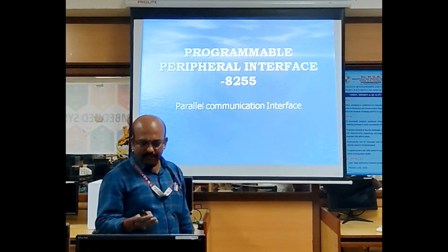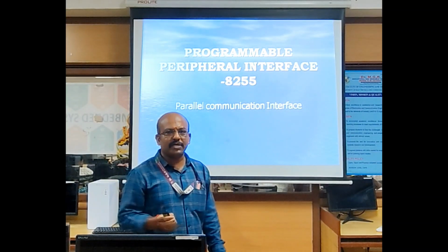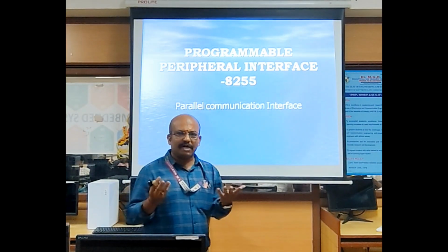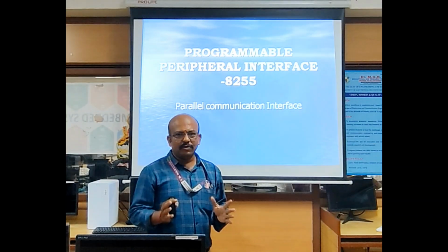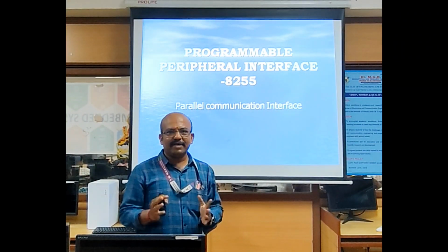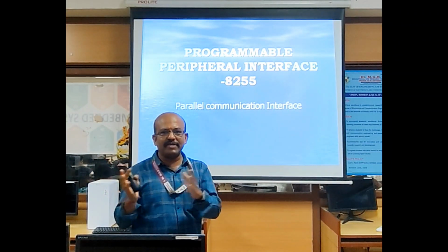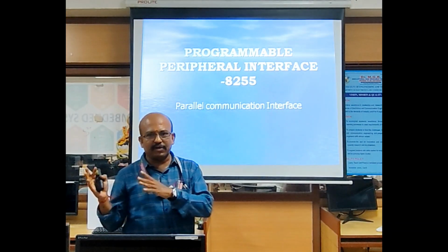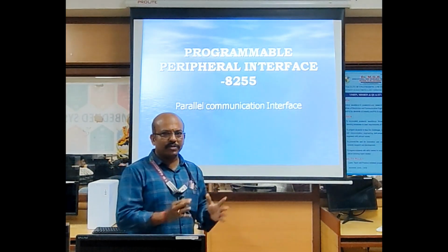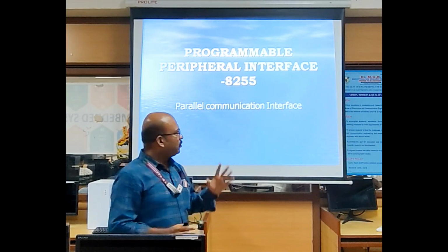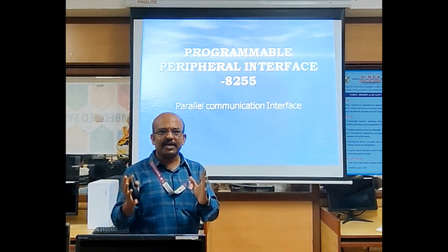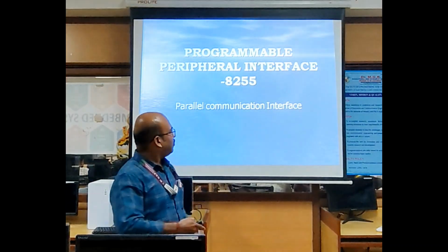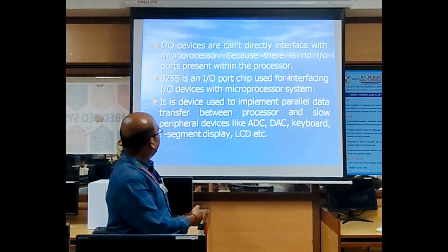In a microprocessor, if you connect any input device or output device, we need ports. The ports are not available in the processor. So we need some interface that will connect any input output device with the microprocessor. What interface will be suitable for connecting input output devices with the microprocessor? 8255. So through that 8255 only we can connect any input output device with the processor, right? So this is the need of 8255.